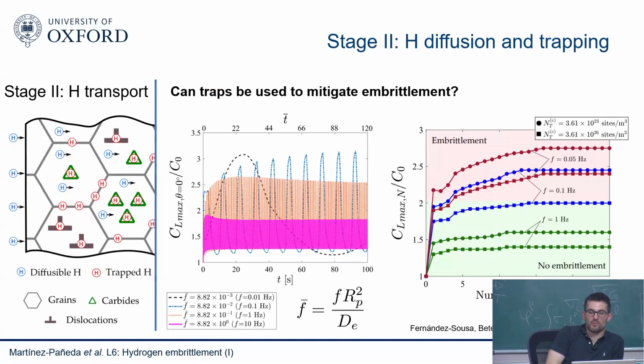So they used to use chromomolybdenovanadium, but these are applications that are very specific. They will store hydrogen in pressure vessels for a limited amount of time. They will change the temperature. There will be a cooling and a heating. The hydrogen will leave the component, and it will be distributed within the metal, and it will change the distribution due to the change in temperature. So you did get this distribution of hydrogen within the lattice to traps due to change in temperature. So you will get hydrogen going to the carbides, and you will see less embrittlement. So it has worked, this idea.